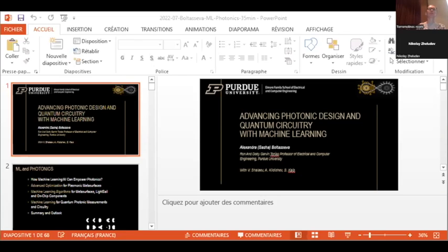This concept is called thermal photovoltaics. And essentially it is a redirection or re-emission of the radiation in such a way that it is mostly emitting in the band where it can be effectively absorbed. So if we look at the spectrum and how we talk about it spectrally, in the shaded region here, you have the working band of the photovoltaic cell. This is gallium antimonide in this case specifically.